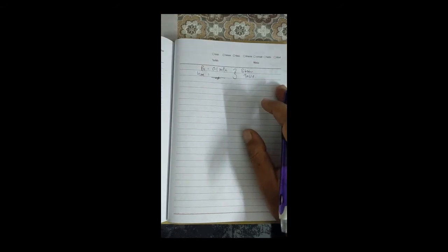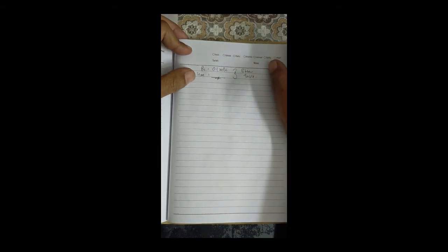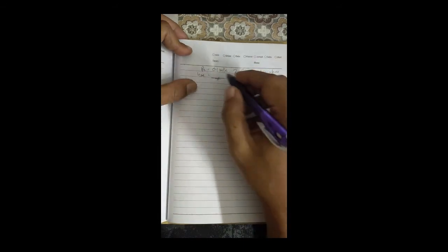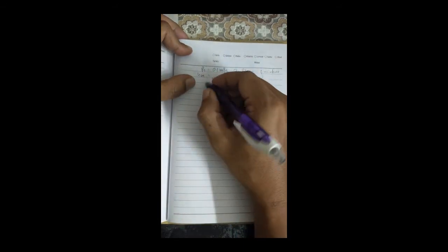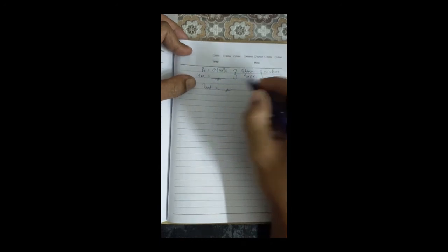In the question it states the quality of the steam, which means it's in the mixture. It's a hint from the question. So basically it's in the mixture. So from the steam table, you can know the temperature. So Tsat. Alright, thank you.